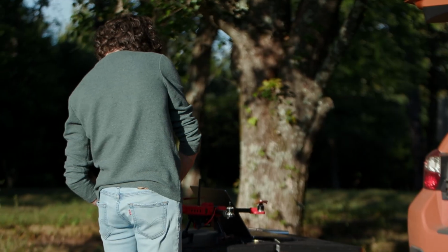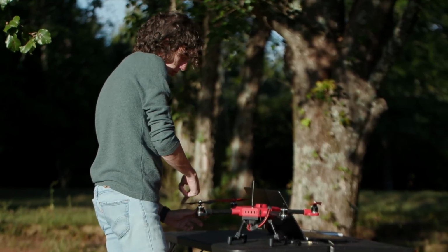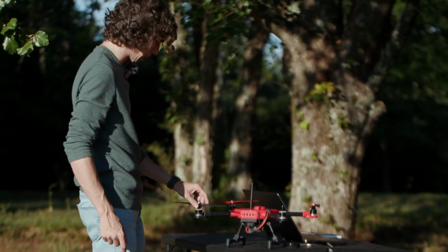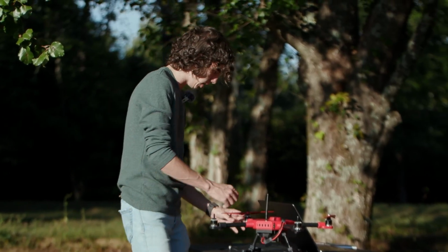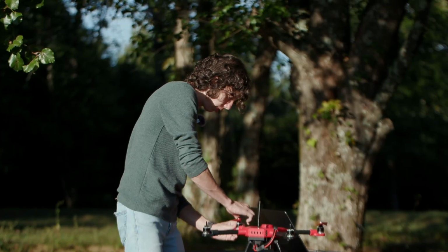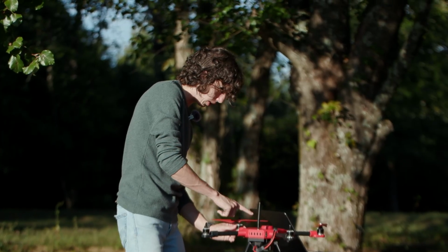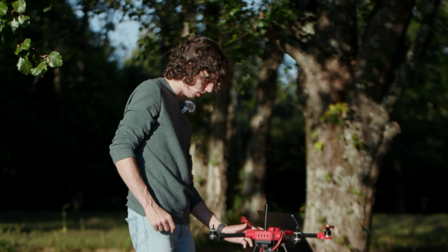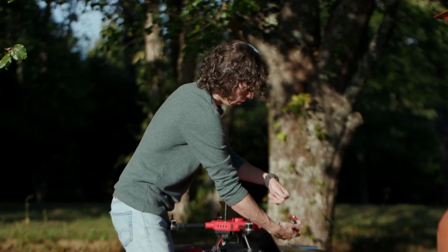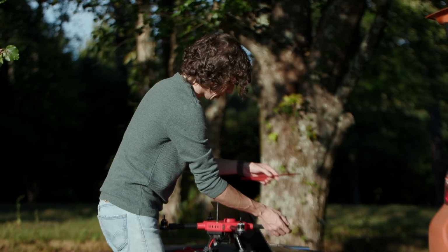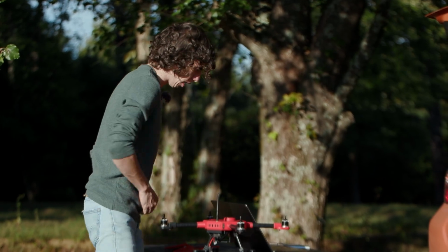I'm taking off the props because we'll probably just want to do a quick motor test once all the parameters are set up, even though following our document we shouldn't need to do so, but it can't hurt to really do a quick double check just to make sure all the motors are spinning the right direction. And as you could probably imagine, you don't want to do that with the prop still on unless you're meaning to fly.